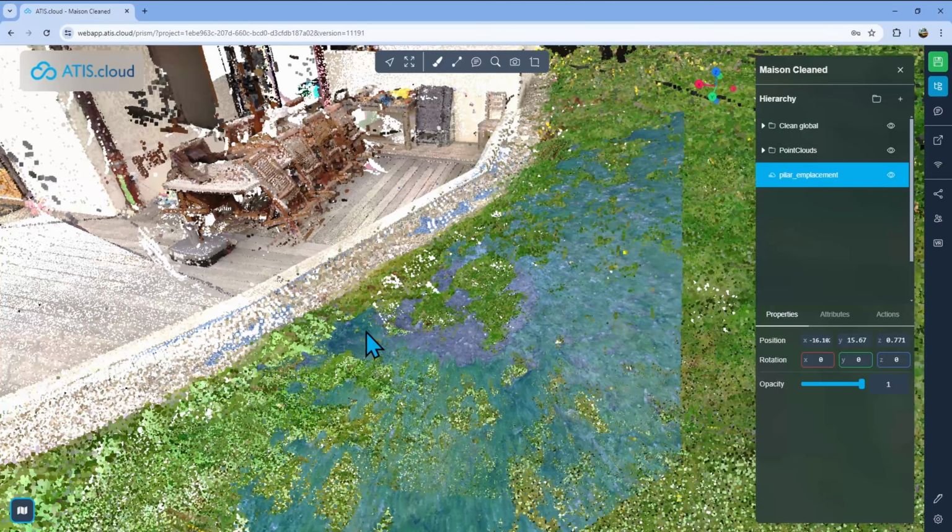So if I just go into Sketchfab right here and search for solar panel, I'll have a few, and for example here that's 72, that looks pretty similar to what I have here. I'm actually going to take that one, and then I just click add to app, and it will load it into my project, and I'll be able to place it. I'll just check the size before I import it, and then I'll just duplicate it as many times as I need to have my whole roof made.